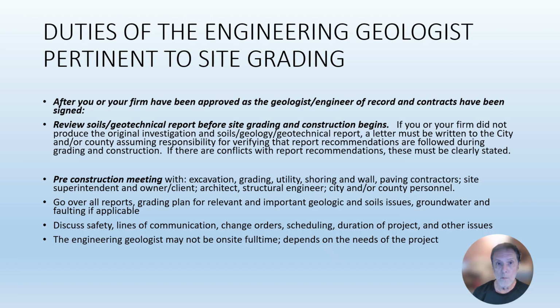So here we go. What are the duties of the engineering geologist pertinent to site grading? I'm not going to go through all this in detail. You can read this for yourself. You or your firm have to be approved as a geologist of record. You have to have signed contracts. You need to review the soil or geotechnical report before grading actually begins. This is extremely important. You need to know what the recommendations are, especially if you didn't do the investigation yourself, if another company did it.